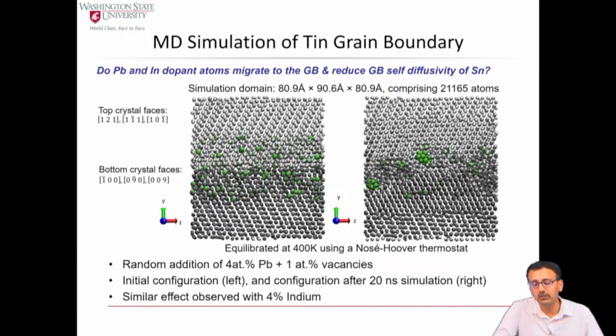And we also modeled indium atoms as dopants added to these systems. Molecular dynamic simulations are able to look at the evolution of these structures with time to get to energy minimized structures, and what that does to the diffusion of these atoms across the grain boundary. So this is again an application we will look at in detail after I introduce the method.